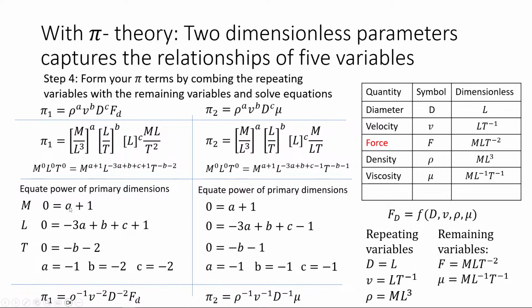Basically, you find the value of A and the value of B and the value of C that will also make this dimensionless. Because remember, dimensional homogeneity means what? If the left hand side is dimensionless, the right hand side should also be dimensionless. So I find the value of A, B, and C that makes the right hand side dimensionless. So you do this, and then you substitute here, and then you repeat the same here. So that's your repeating variables, that's your dependent variable.